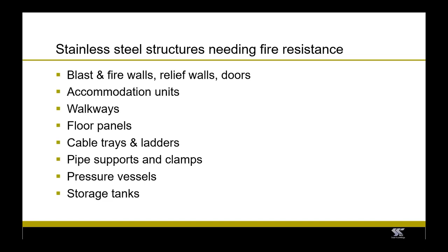So the only difference is that the yield strength and the elastic modulus that are used in the resistance equations have to be the ones for elevated temperatures. So the value of the yield strength and the elastic modulus at elevated temperature are given as a proportion of the value for room temperature. And this is achieved through retention factors, which are basically the ratio between the property at elevated temperatures and at room temperature.